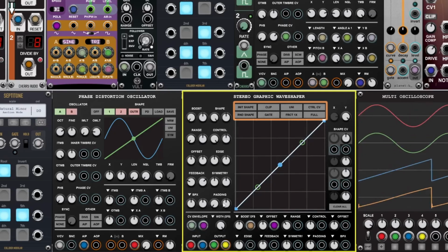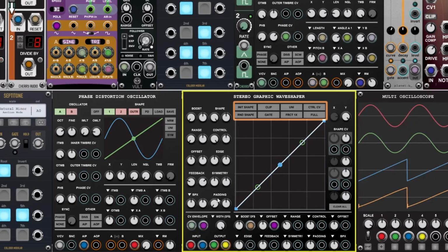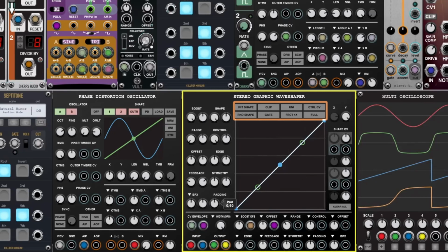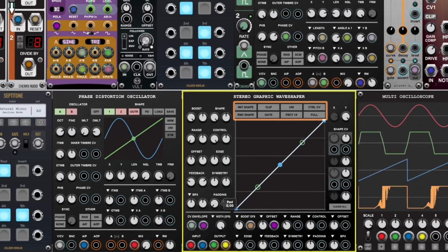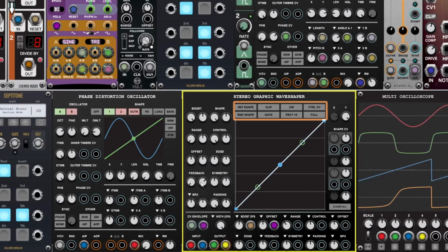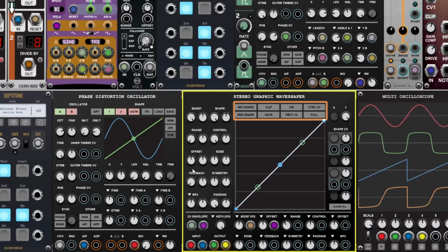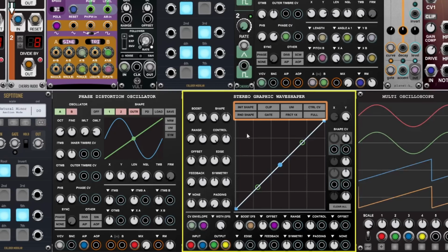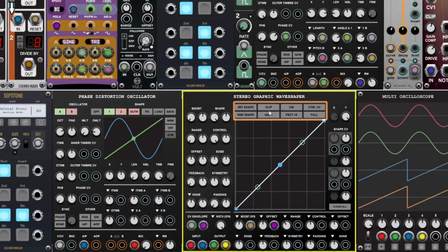The strength of the overflow protection is influenced by the padding knob. With padding, you can turn the aforementioned hard clipper into a neat little soft clipper. Moreover, the selected mode has a huge impact on feedback circuits, as the overflow protection is within the feedback loop, regardless of selected feedback mode. It's also important to note that the overshooting signal peaks are dealt with before the actual shaper, and that there is no further overshoot handling after the shaper.